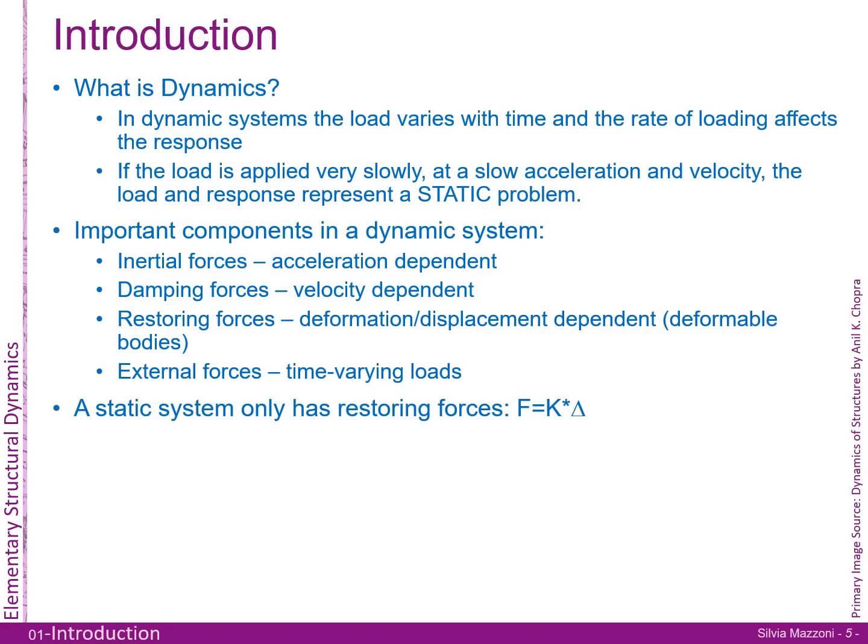The very first question is, what is dynamics? Well, in a dynamic system, the load varies with time, and the rate of loading affects the response. So for example, you could say that gravity is a load that could vary with time, or maybe as you're building a structure, the loads vary with time because you're building more and more. And so yes, you have a function of time, but then the second part is the rate of loading affecting the response. So if you're building your building and you slowly add on columns and beams and floors and walls, you're not really changing what is going on with the structure.